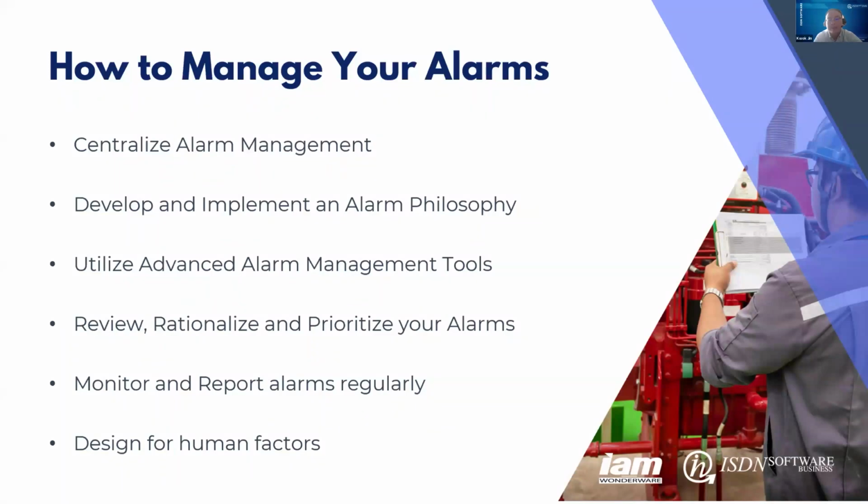If this happens again, make it a lower priority so that I focus on the more important alarms coming in. This will help your operators focus on managing the process instead of simply servicing the alarms that are constantly coming in.